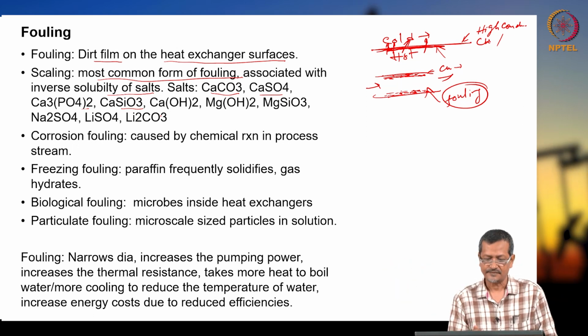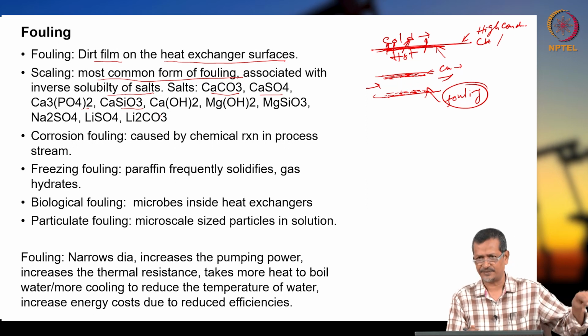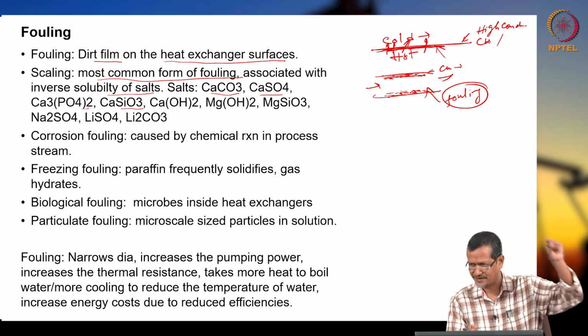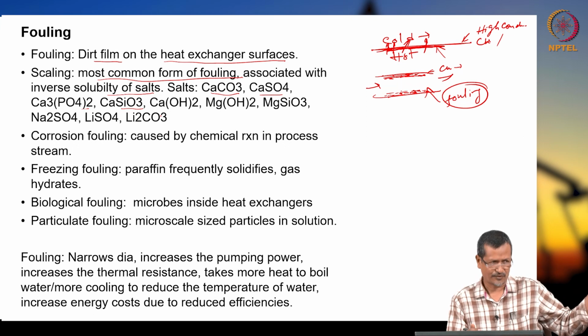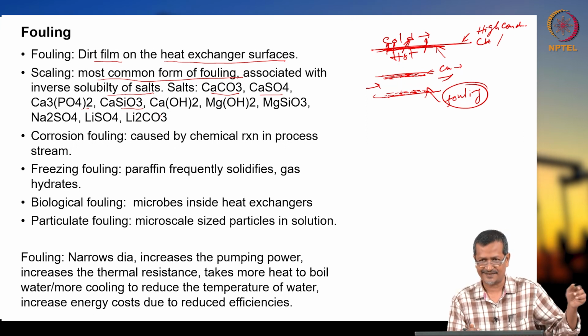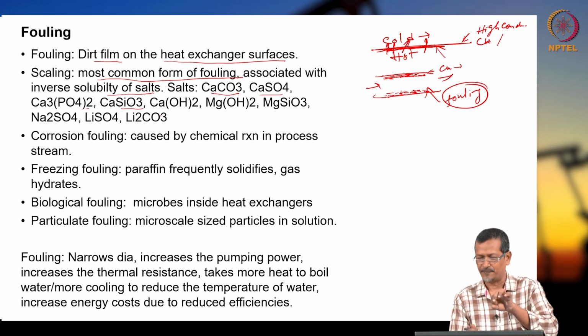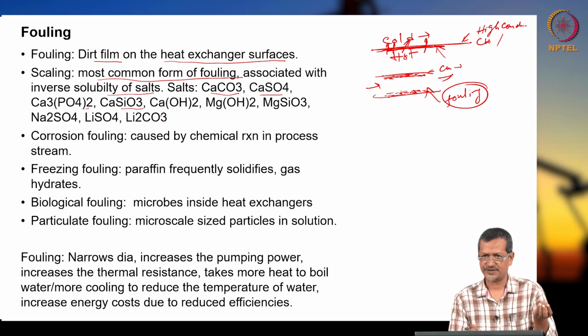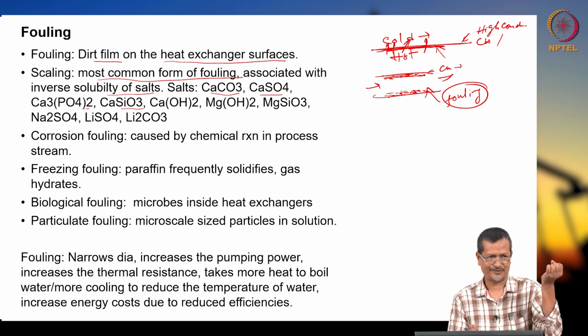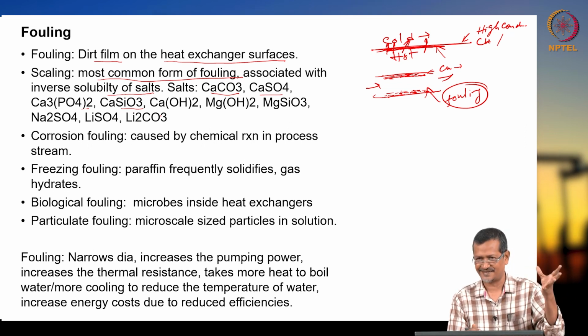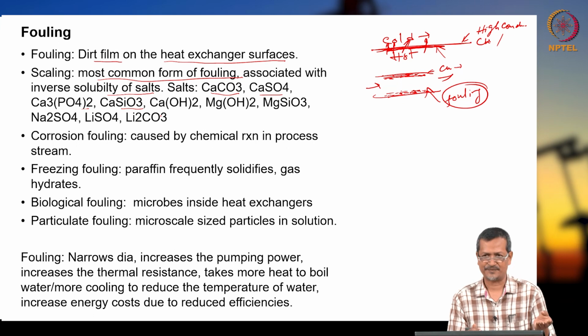Okay. So in that case, because continuously they will be cooling and evaporating this water system, and feed water also will be coming. If the feed water is dirty, then scaling will be deposited, and the pipe can be blocked. And if the pipe is blocked and you are supplying constant heat, what will happen? Pressure will be increasing without limit. So in that case, a burst or accident can be possible. Okay, heat can be shooting up.